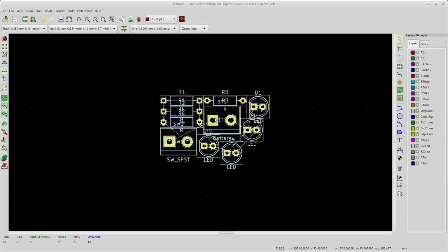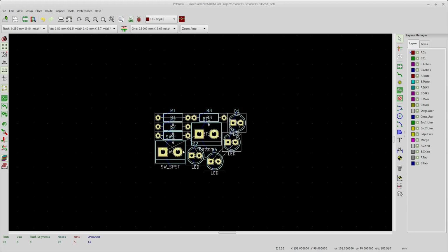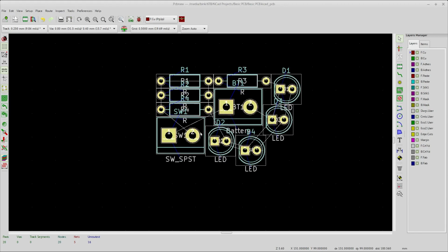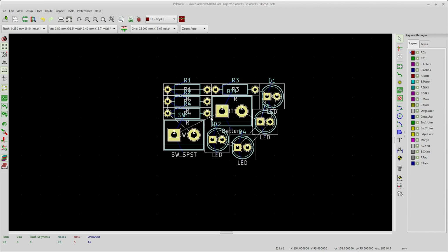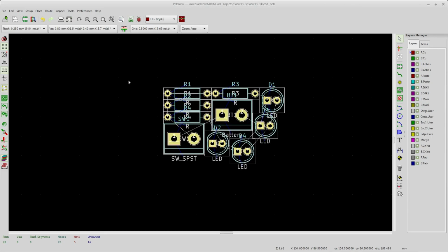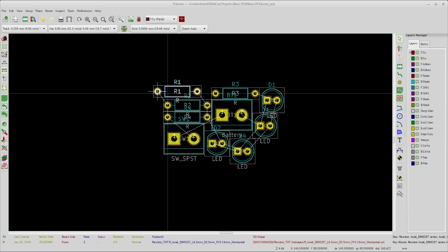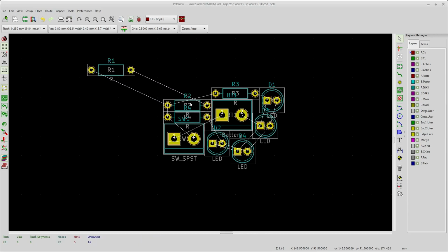So that's good. And then you start to move this thing around. I kind of wish it might be in here. Haven't found it yet to expand it even further. But you basically come over the top of each one of these things, hit M to move. Oops. Click away, click in the background. M to move, but be careful that you don't just grab a pad or words like right there. You see how I just grabbed the words, hit escape to clip that off there.